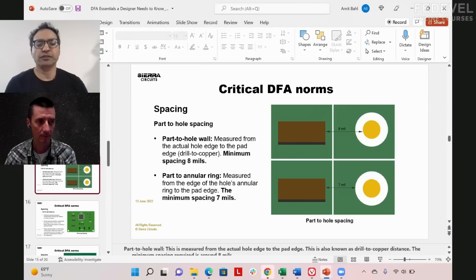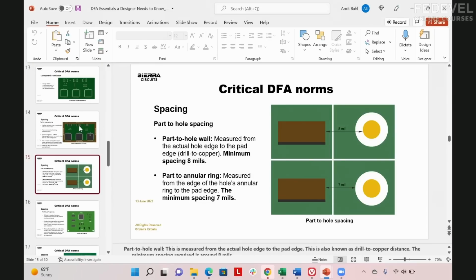And then, for a PCB manufacturer to ship a good product, it's called drill to copper, right? But the part can possibly overhang. Is that bad? Probably not. So I would say drill to copper is important for a fab house, and it's important for the assembly facility as well. The critical dimension there is the solder mask web.